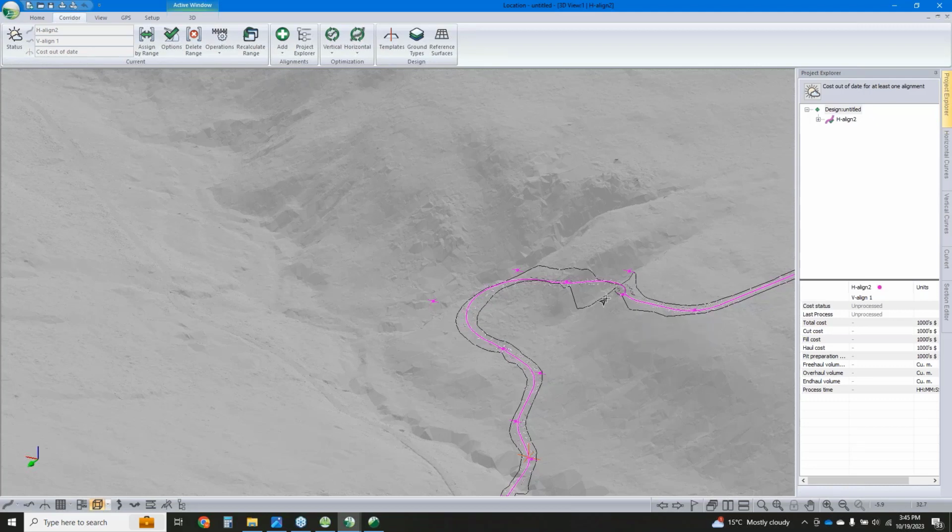So you can measure that out further if there's a bench underneath you that you want to capture. The other side of it is, while I was falling off the model there, in reality, I probably don't want to fill down there anyway. So in the case where I use the vertical optimizer, I should have put in a full bench constraint, because really I wanted to be in full bench through there.